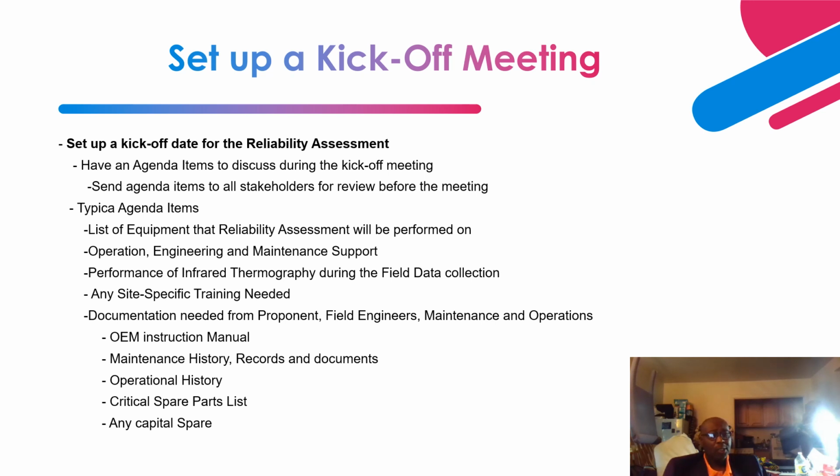And sometimes, depending on the location of the substation, and also the criticality of that transformer, and the criticality of the customers that it feeds, you can have a capital spare. Let's say you have 5 or 6 substations that are in very close proximity to each other. You can identify, depending on the design and the rating of those transformers, a capital spare that will be a spare for these transformers if any of them should fail.